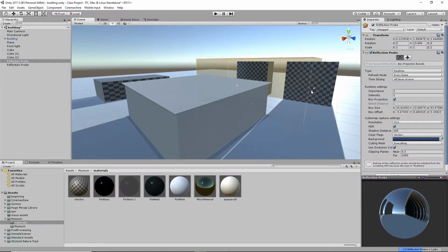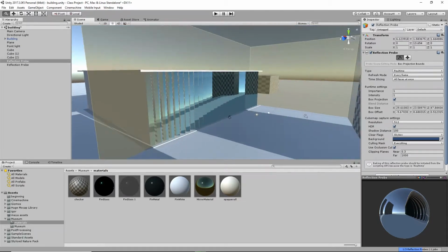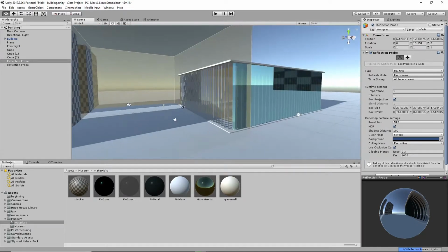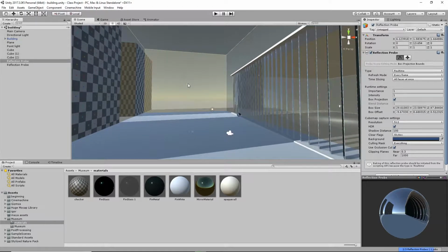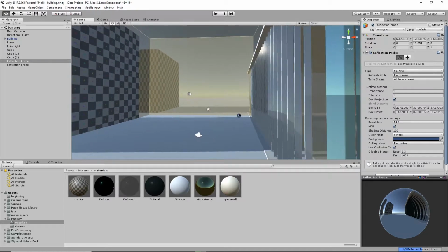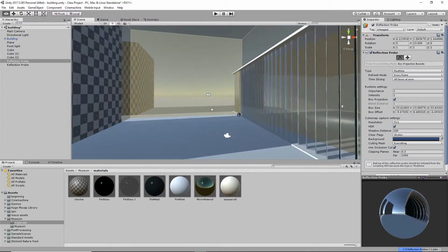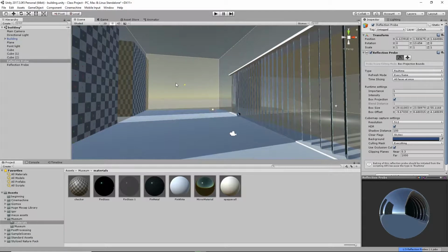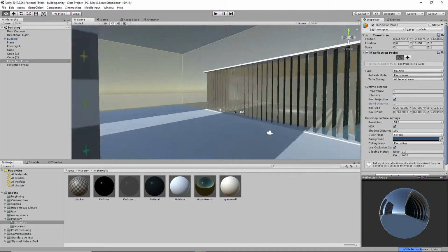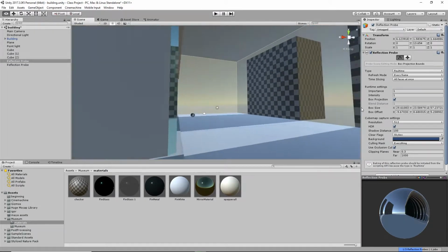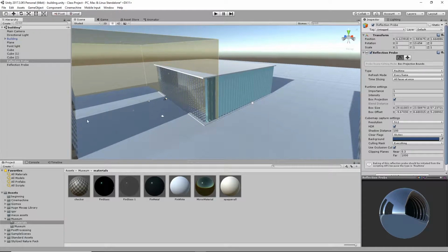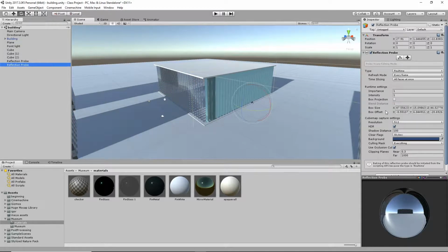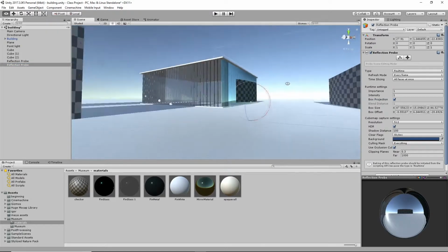We don't have to, let me see, I think it projects out beyond. Yeah, because then you can see the building in the far corner over there. If I move this, it probably doesn't matter, but the reflection looks a lot more realistic. So let's do that on the opposite probe too. Set it for box projection, that little check box there. There we go.